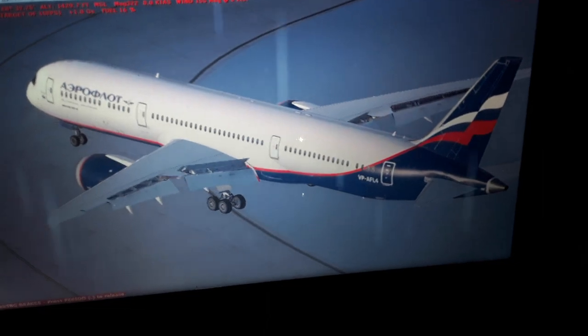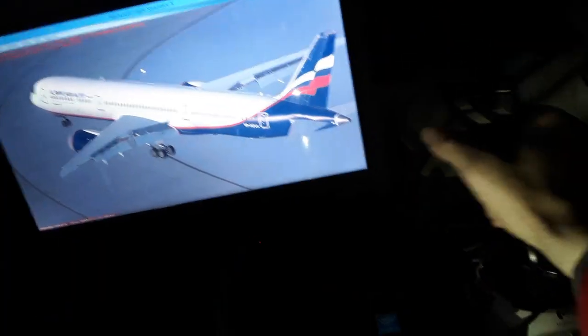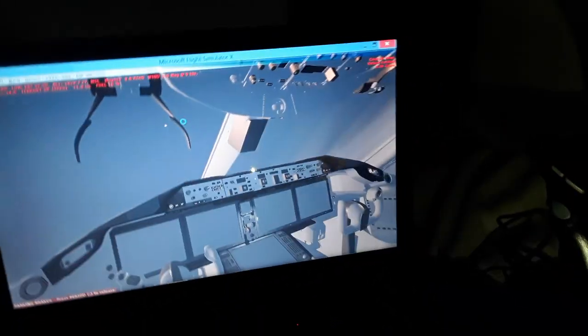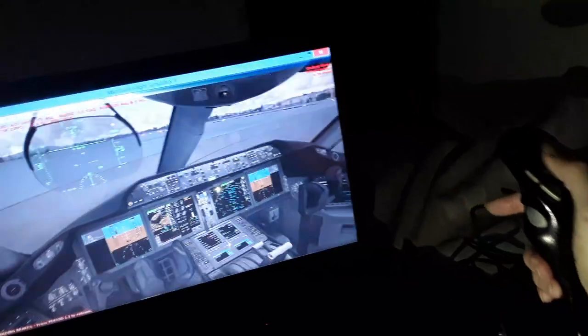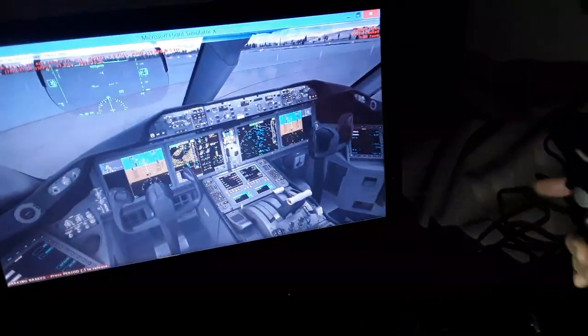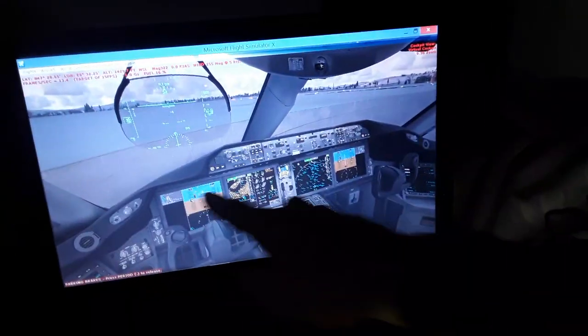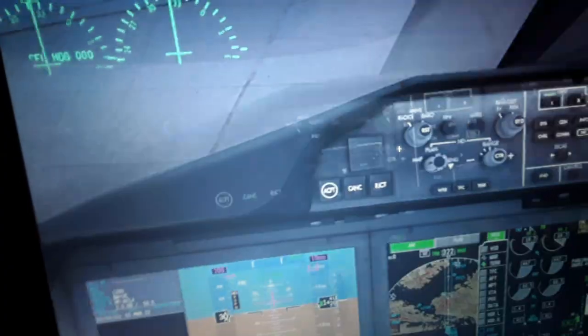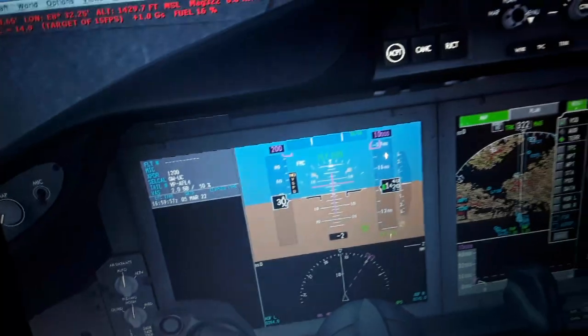So this is the aerodynamics of the aircraft that we need to know when flying, also for controlling the flight controls. I'll show you a little bit more of the flight controls now. So we use the elevator for climb and descent. We need to pay attention also to the airspeed, always to be above the stall speed, and the angle of attack. You can see also the vertical rate of climb and descent of the aircraft over here, in more detail.